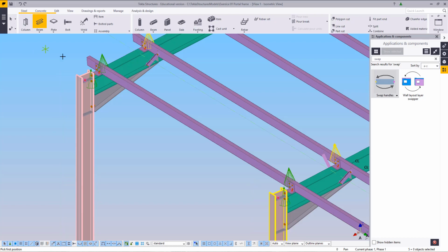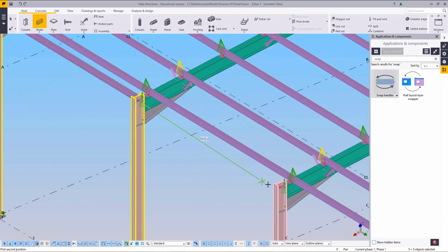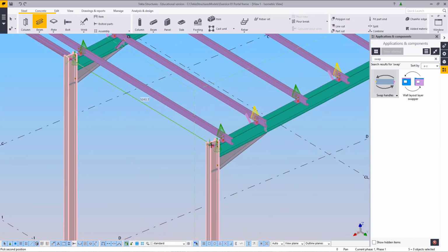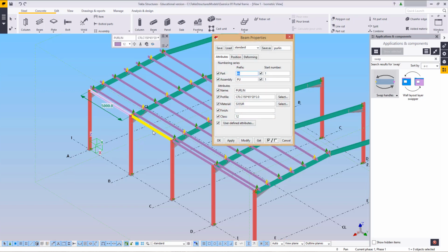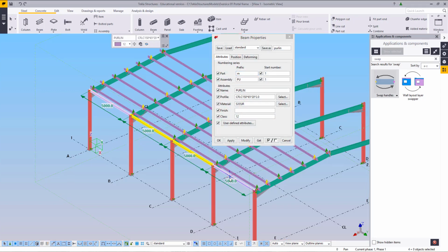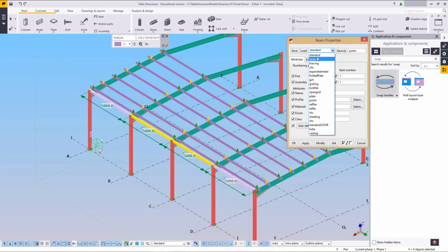So, firstly, put that in from there to there. As you can see, I'm currently still on the rafter. Well, sorry, I'm still on the purlin, and that doesn't matter. I'll simply open up one of them, select all of them, get to my properties, and from here I'm going to load the pipe. For this purpose, I think the 114 by 3mm pipe will work just fine.